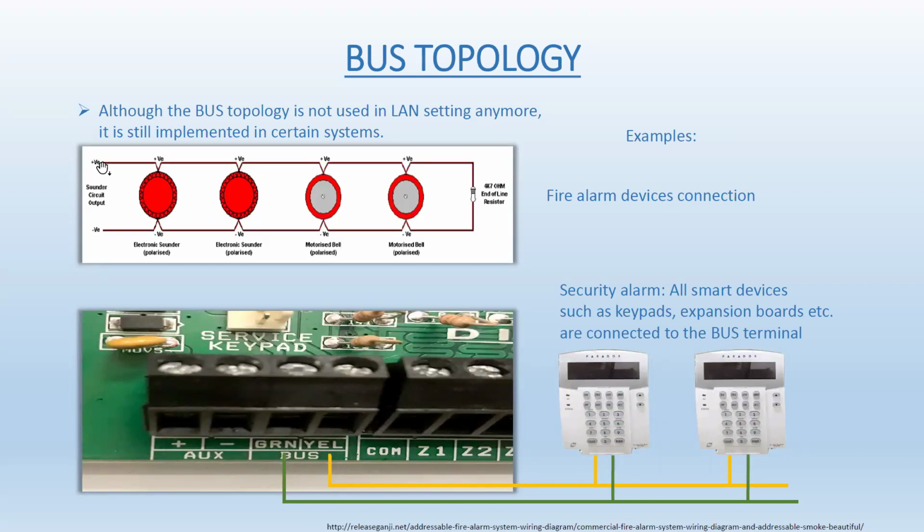But what the zone wants to see at the end of the line is a resistor of a certain resistance, and it's closed here. Look, it's actually named the end of line resistor. This one here is 4.7 kilo ohms. It's a common resistance for an end of line resistor for fire alarm. But if you have different panels, sometimes those could slightly vary. So you have to choose the proper one for the proper panel. But 4.7 is a quite common one, right?